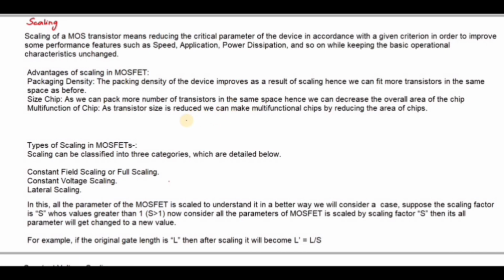These several indicators are called figures of merit. That is, minimum feature size, power dissipation, maximum operating frequencies, and reducing the production cost come under the figure of merit. So the figure of merit is improved by shrinking the dimensions of the transistors, interconnections, and separation between the features, and by adjusting the doping levels and supply voltage.